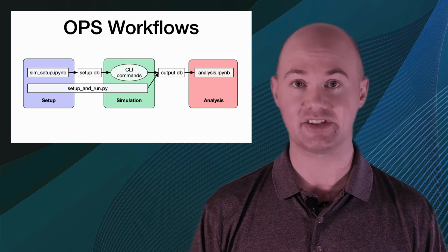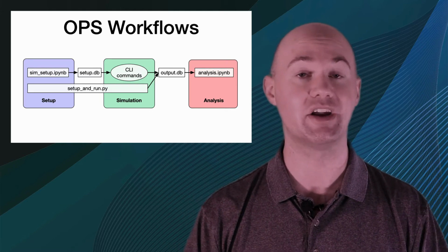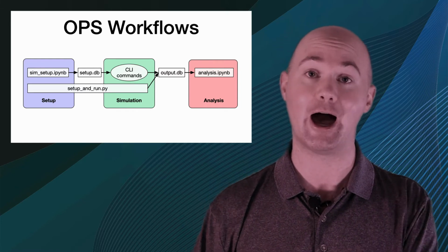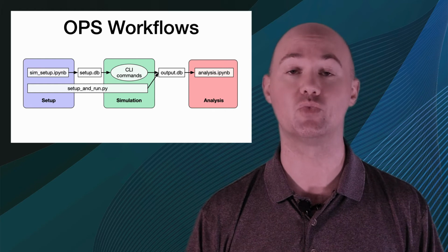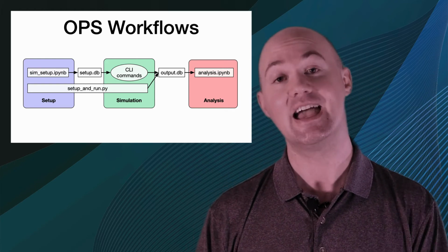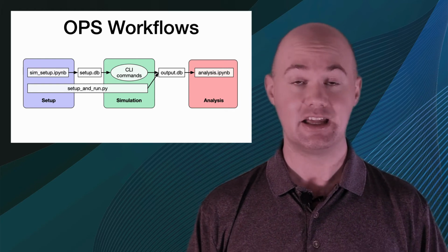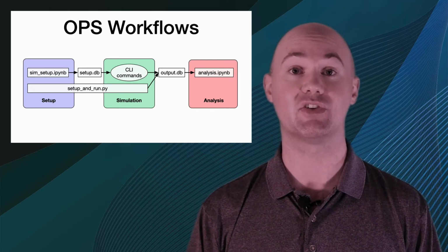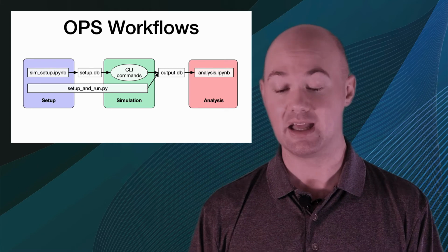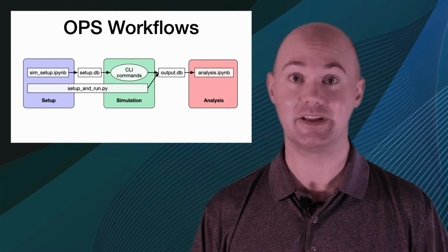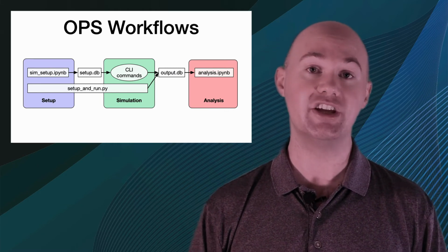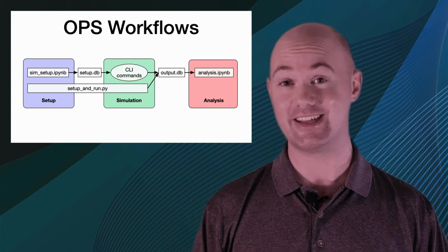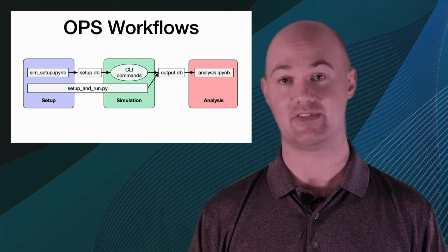So you can reuse those objects in the sense that if you're running one TPS simulation, but you really want to run multiple copies of it at the same time, you can reuse everything from your setup.db, and it will make your analysis easier. Possibly you're doing different kinds of simulations. First you're doing a TPS simulation, then you're doing a committer. If you reuse the setup.db for the definitions of your states, you're guaranteed that you have exactly identical state definitions.